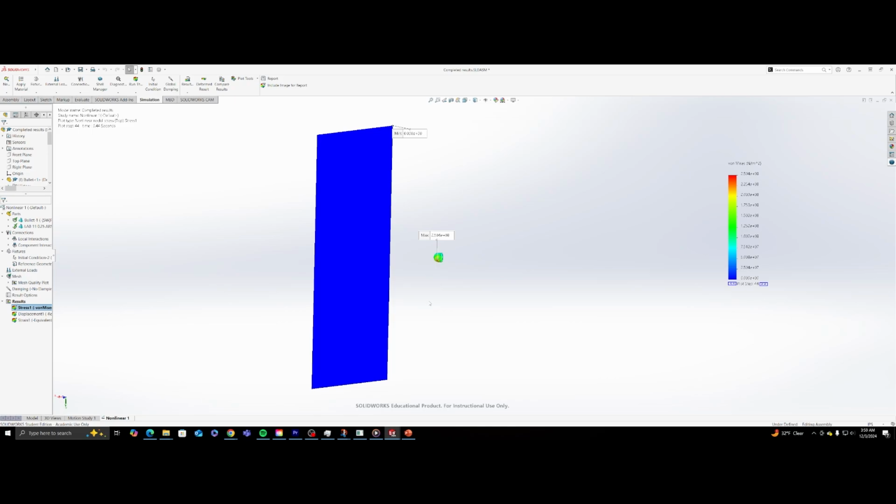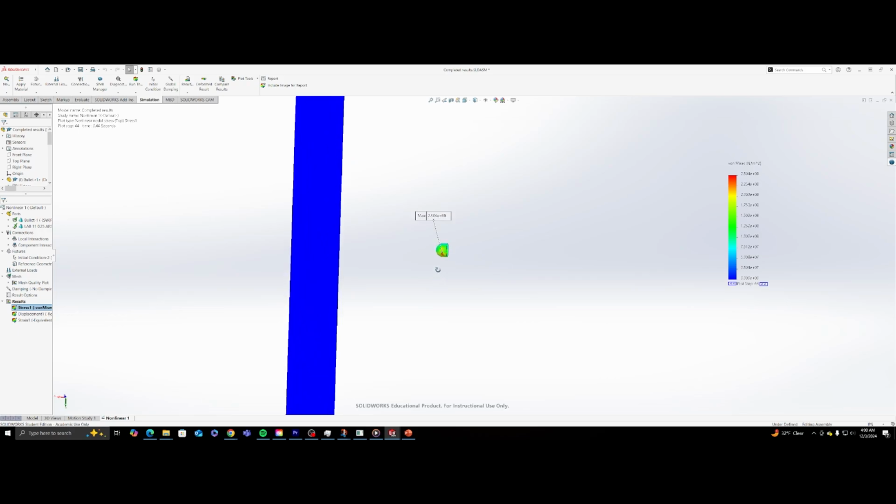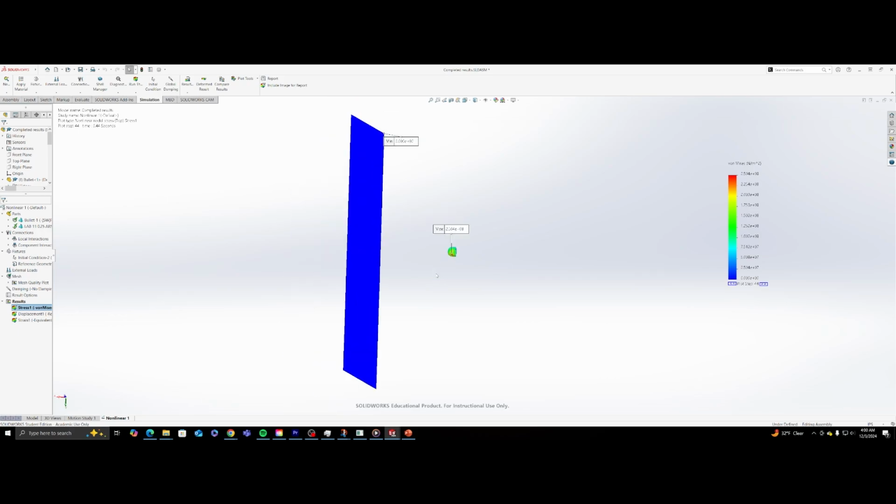can make some assumptions and limit the time. You don't need to have a huge mesh on your plate, that's flat. You can define it. You could add some damping. We didn't add damping. That was part of the reason that it took so long. So that's a big reason why we had a lot of issues getting stuff to run, and hopefully that'll help you when you do your mesh or your simulation.